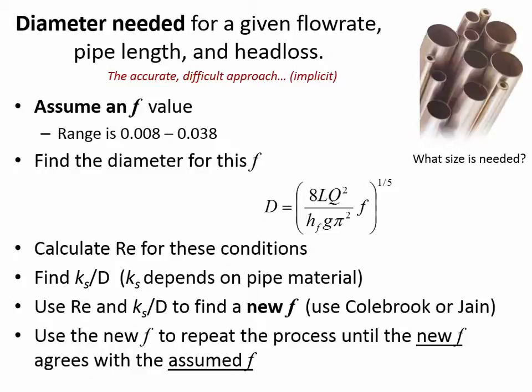But we don't know what the velocity of the water through the pipe is until we know the diameter. But we don't know the diameter until we know the velocity. You see, I could say that a few more times to make my point. In the example we're going to work, we're going to have to go back and forth 4 times, starting with a guess, and then honing in a little more on the final answer for the velocity of the water going through that pipe.